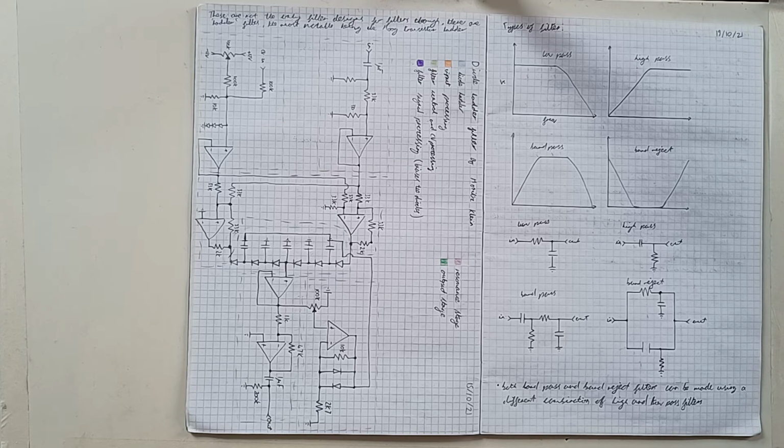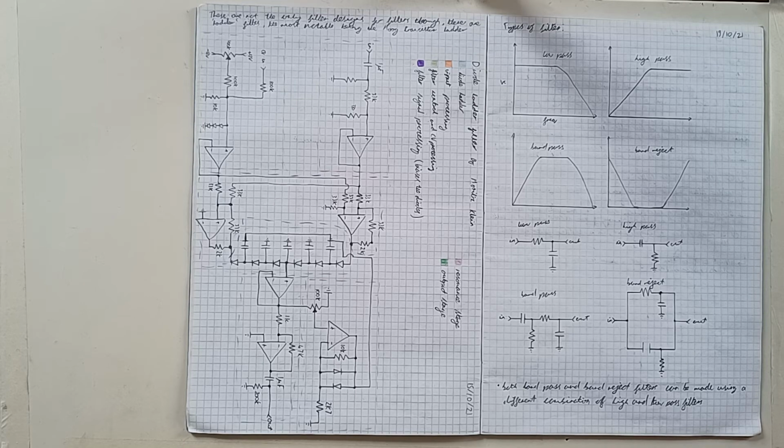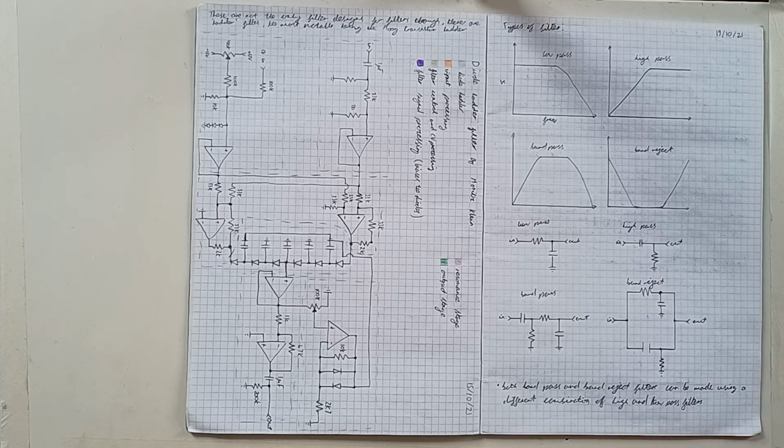I didn't look into it for my project, as I knew from prior knowledge that you have to use matched transistor pairs for the transistors, which can be quite a hassle to either buy or find from your own transistors. So I chose to stay to more regular components such as diodes. So whilst it is a very key example to note, I didn't look into it personally.